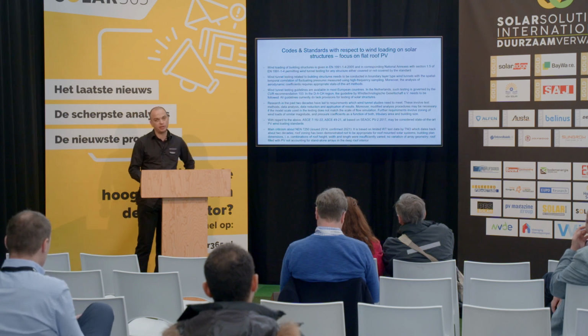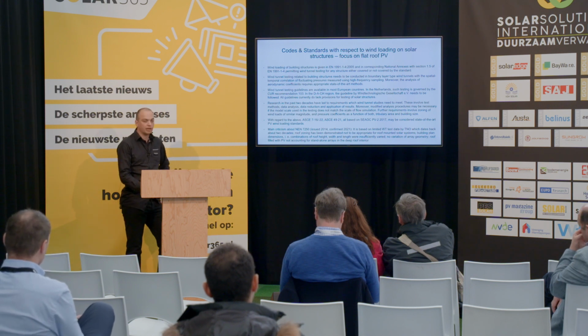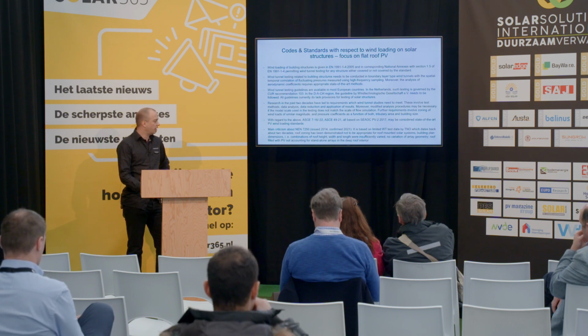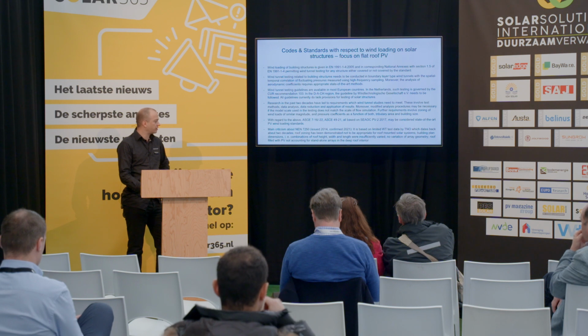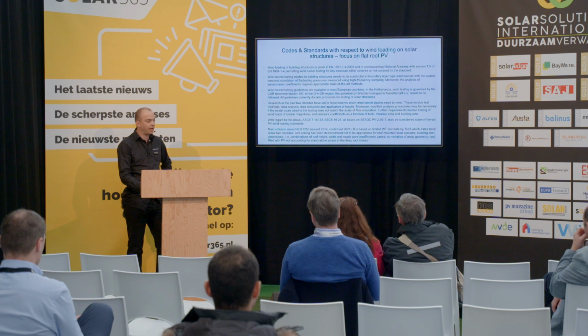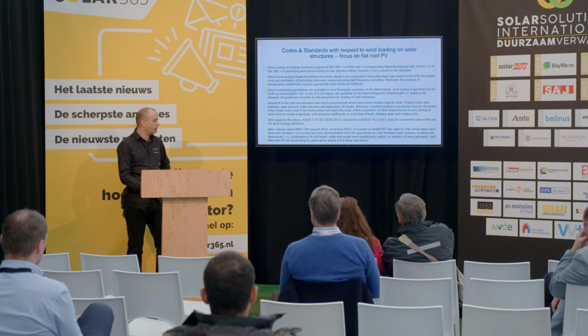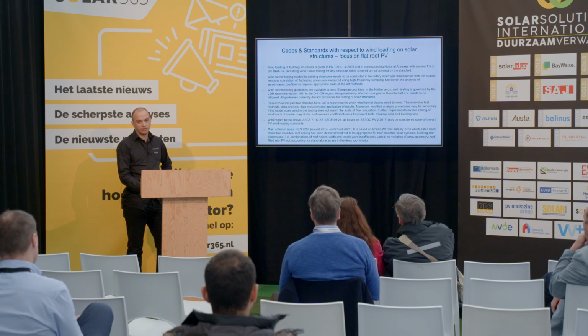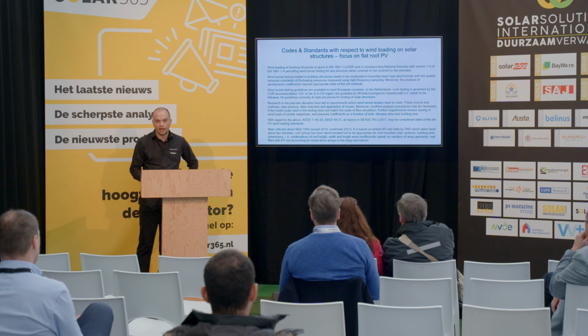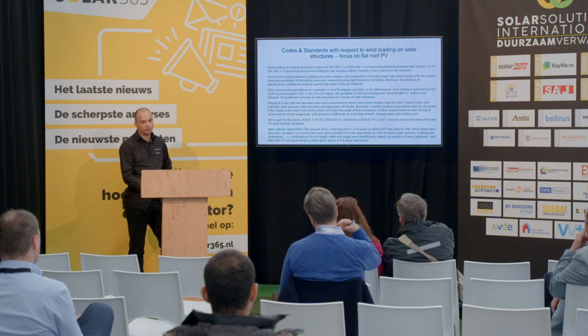Roof zoning has been demonstrated not to be appropriate for roof-mounted structures. The building plan dimensions, roof height, width and length were insufficiently varied, and there was no study of array geometry. Usually when you see a wind tunnel test according to the NEN, the roof is filled with PV, not accounting for any stand-alone arrays somewhere else on the roof, such as in the deep roof interior.